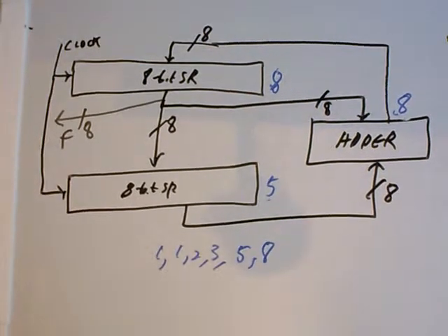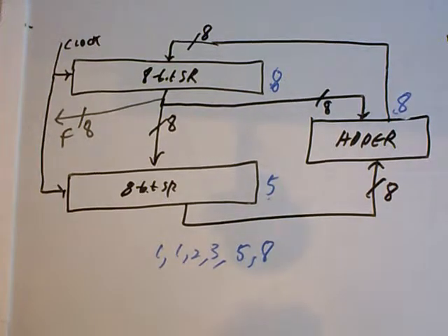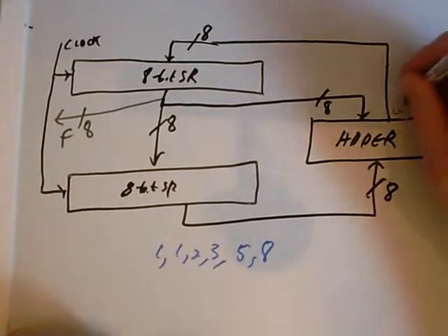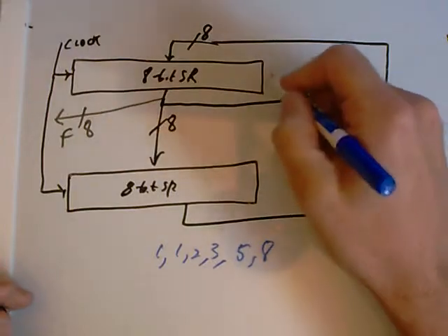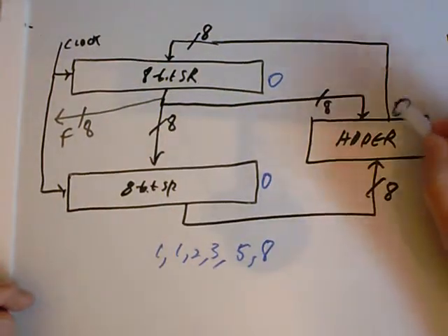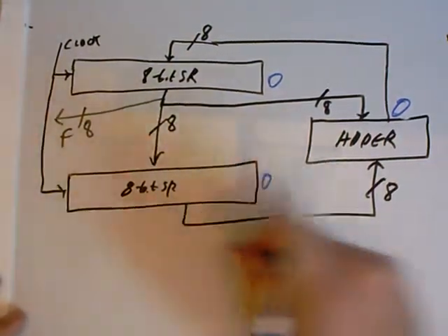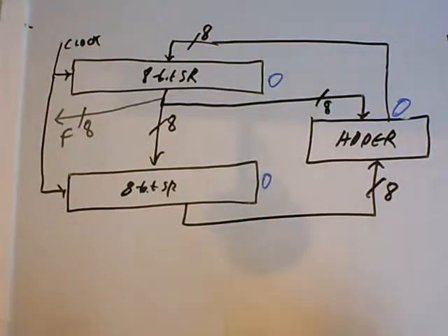So we're going to lay this out using the loader tool and simulate it using the simulator. The one trick on this is that we will need to seed this system, because when we first begin, both of these registers are going to have a value of 0, which means the adder will output a 0, which means each time that we tick the clock, we're just going to be loading zeros back into each register. So we're going to need to seed this somehow.